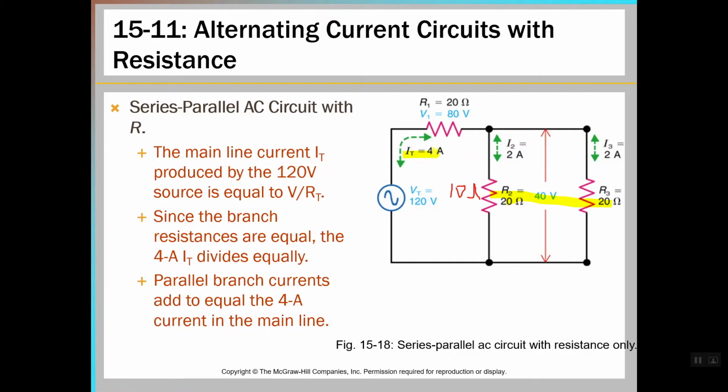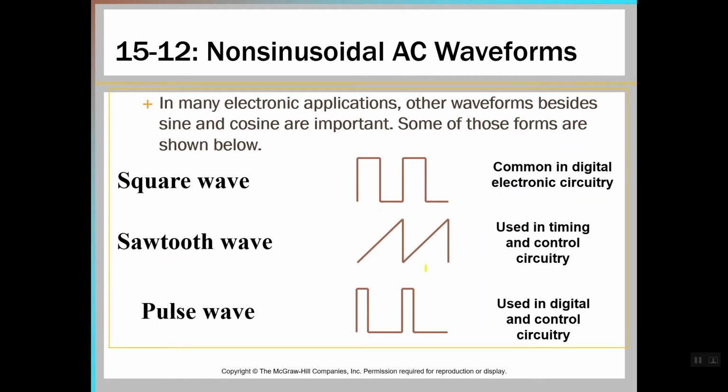Amps, which means my voltage there is 80. 120 minus 80 gives me my 40 volts. And since they're the same voltage there, 40 divided by 20 gives me 2. Boom. There we go. Same thing. All this still applies, still works the same way. If you talk about getting into power and all that, it also applies the same.